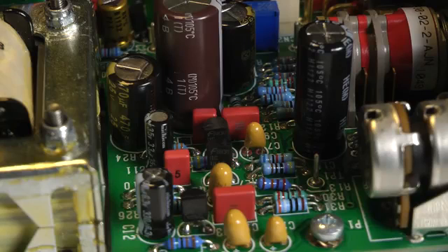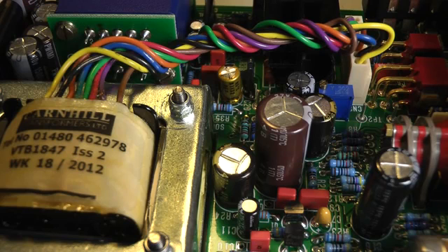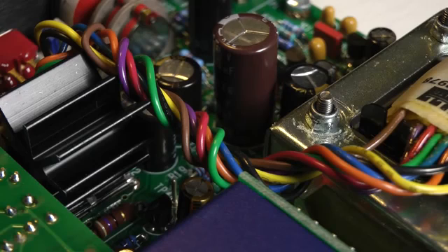Secondly, harmonic distortion or coloration. Harmonic distortion was originally an unwanted side effect of early electronics, but is now recognized as a useful effect. Even integer multiple harmonics tend to thicken the sound, whilst odd integer multiple harmonics can add some brightness. These effects can be subtle and difficult to achieve with other devices such as EQ and exciters.